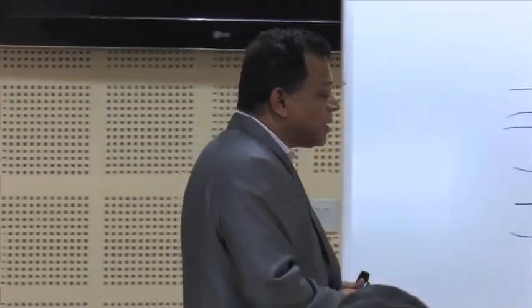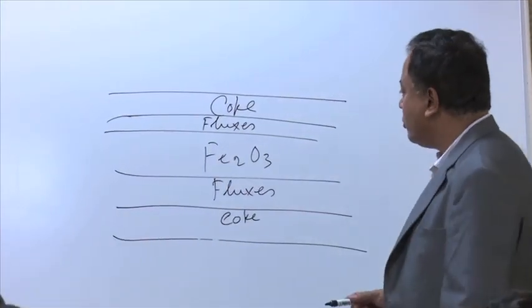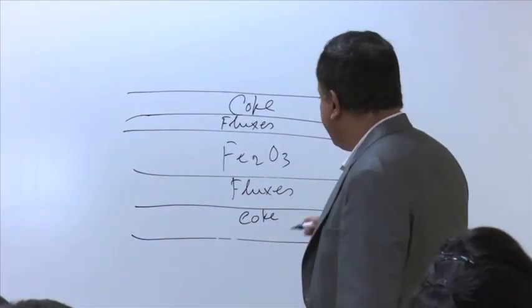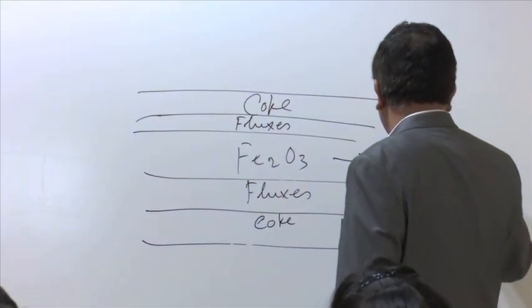So, I cannot charge very fine particles there, because if I have very fine particles, the permeability of my bed will be very low. So, my gas flow will be inconsistent and my reduction kinetics will suffer. That is why there are size restrictions for all these materials, specifically for iron ore. That is what I said, they want minus 40 plus 10 mm particles.